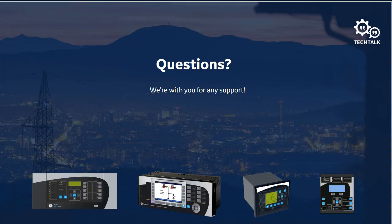Okay, that's a repeat question. What are the impacts of the 61850 standard on the use and interaction of symmetrical components? Well, 61850 is an IEC standard, and there are a lot of things that are defined in that standard, things like communication protocols, engineering tools, logical nodes. Symmetrical components are a mathematical technique, so the two are somewhat divorced from each other.